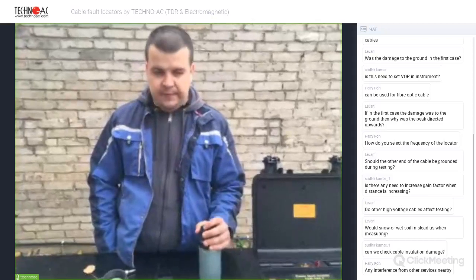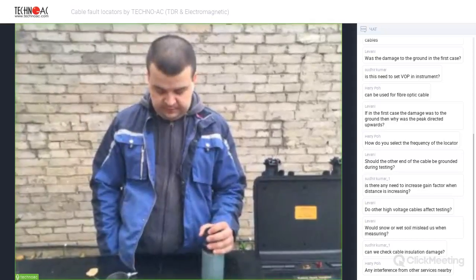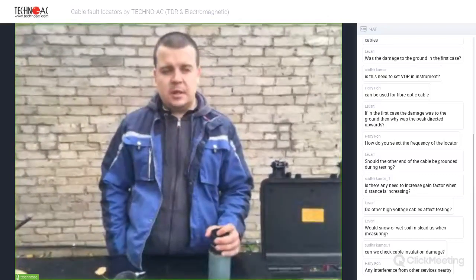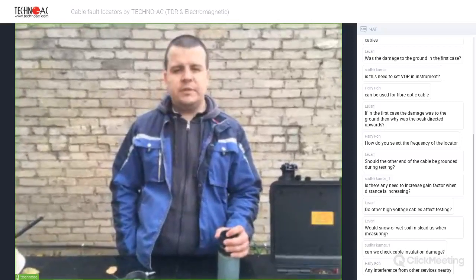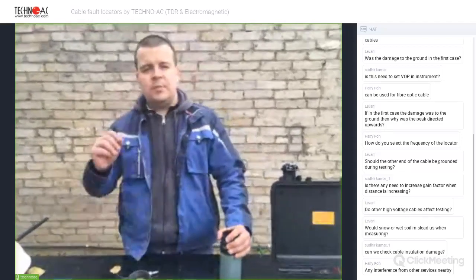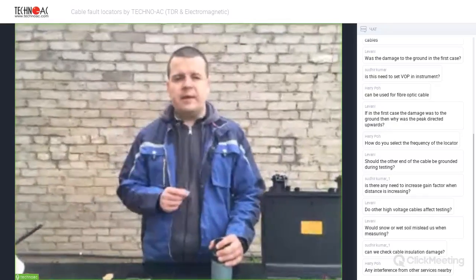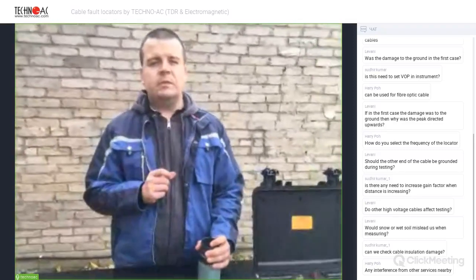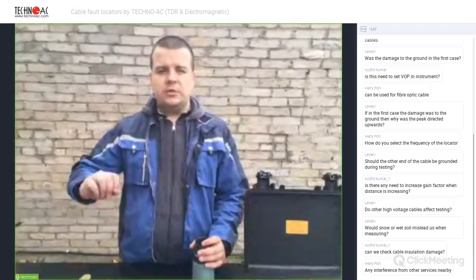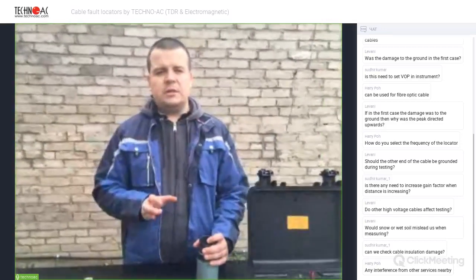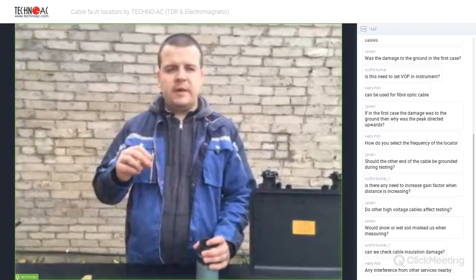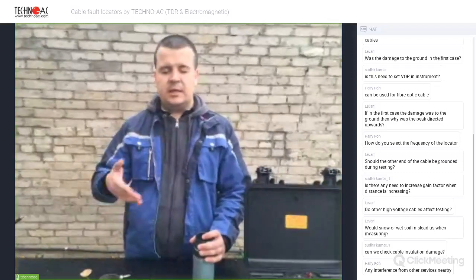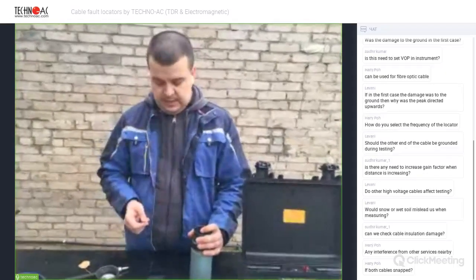I'm having another question here. Any interference from other services nearby? No, I've already replied to this question a couple of minutes ago. There will be no interference because we're connecting to particular phases of the cable, and we're testing the particular cables on a particular frequency. So any interference should be excluded. I also told you that you can use a pinpointing device like an inductive clamp or cable identification accessory.